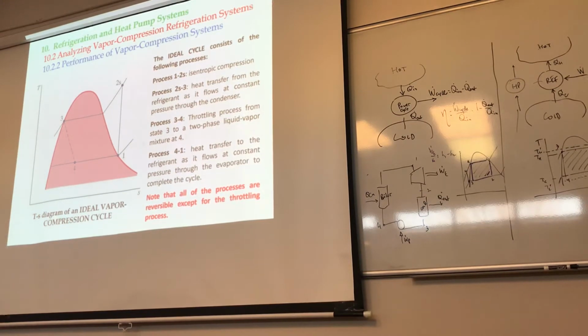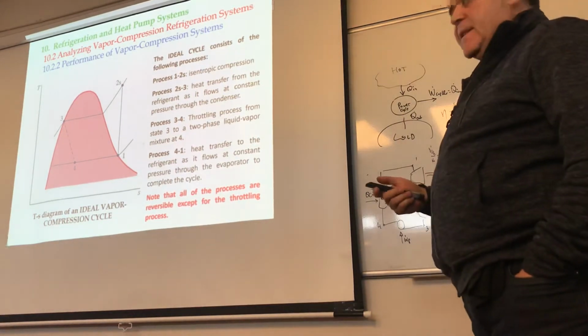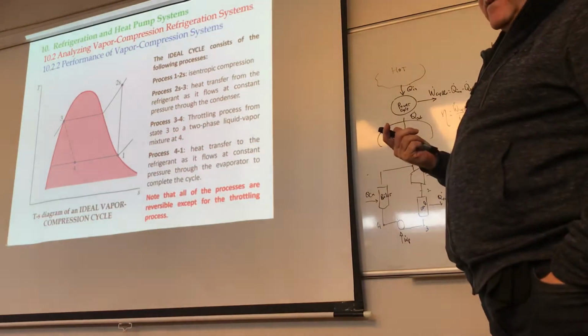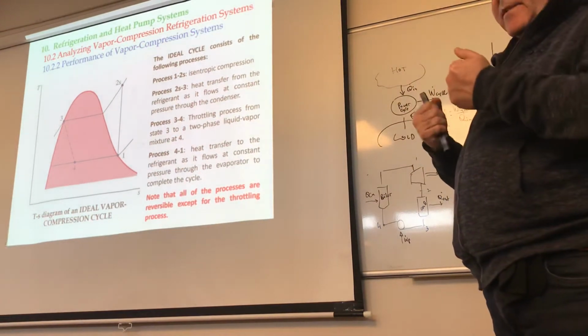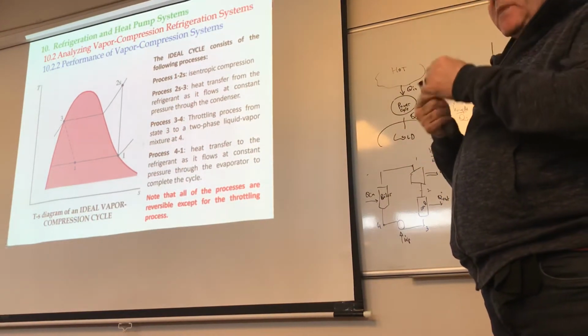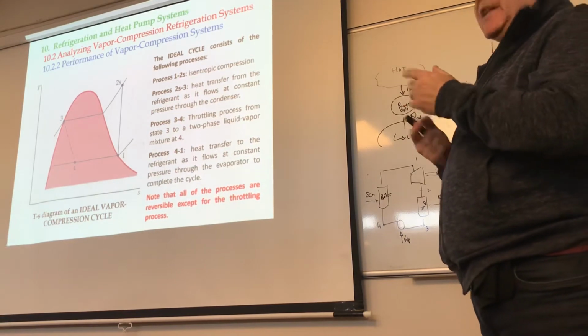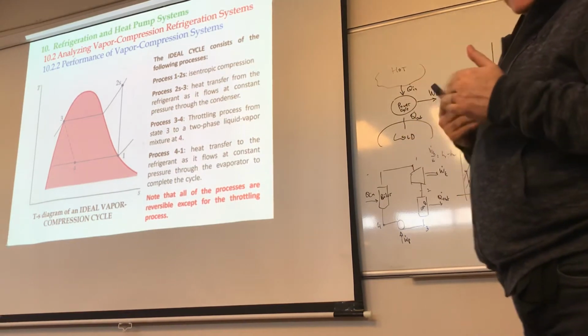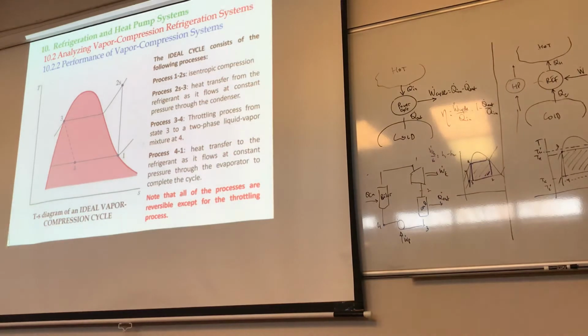But here, why do we have it slanted like this? You think? Because it's not an isentropic process. When you're going through an expansion throttling valve, even though there is no heat transfer, it is not reversible, so it gets accompanied by a slight increase in entropy. That's why we show it like this, okay?